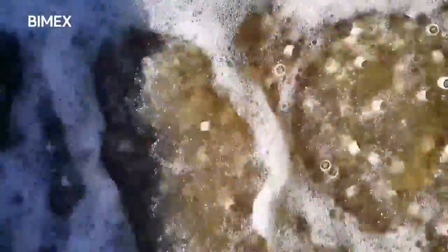Almost half of the aeration tank is filled with biomedia to increase the biomass population in the aeration tank, thus reducing the required footprint. The biomedia is made of polyethylene and has a large surface area that houses many different kinds of microorganism populations needed for the wastewater treatment. The biomedia has a density slightly less than water and will float in water.